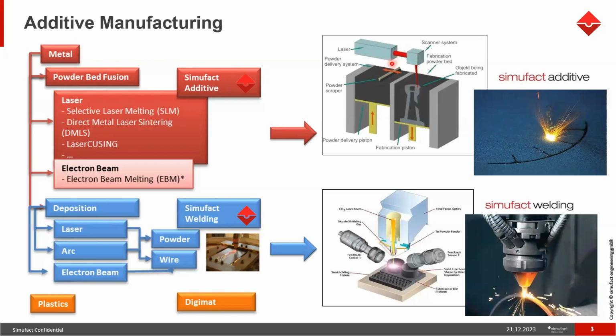So this is a general framework of how the manufacturing process happens. Generally, this particular process uses a laser heat source. There will be a laser which supplies the heat and melts the powder at that particular region. The machine will have slicing software, which slices your CAD model into several layers.